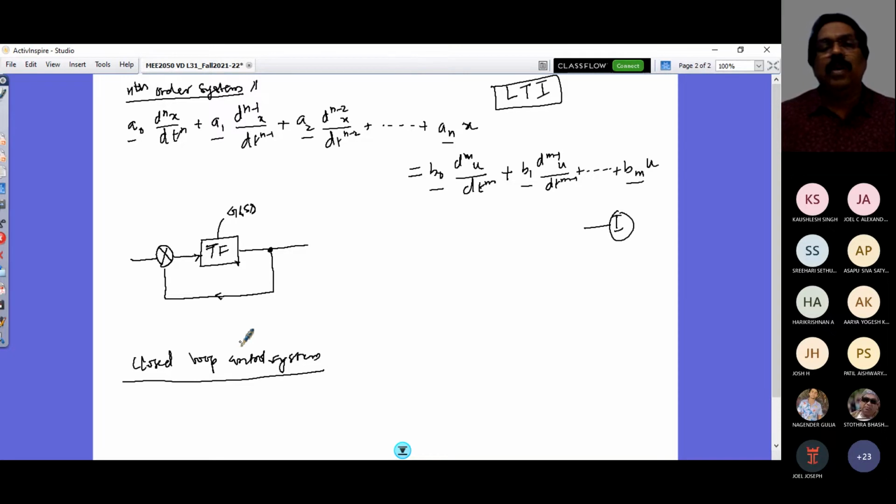You also have a test called a slalom test. So you will have cones in the path, and you have to go in a sinusoidal path. You have to correct your steering and maneuver nicely. So there are many tests that are called closed loop tests. In our earlier part of the course, we looked at open loop tests that find out its tendency, its natural behavior, and so on, right? So now you see this is a simple representation of a control block diagram. I would have my input U of S, and I would have my output X of S.